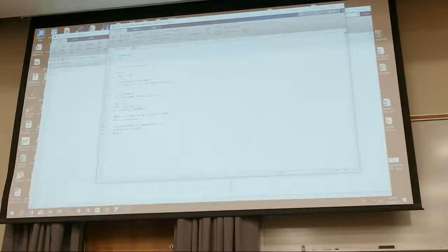But if I go ahead and did what I showed you last time, we take 1 minus exp of this omega. Now this is scaled, right? According to that, times ts, and divide it by j omega, and times the DFT. Now I get something I can directly compare to the actual Fourier transform.